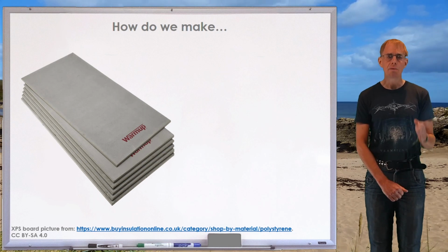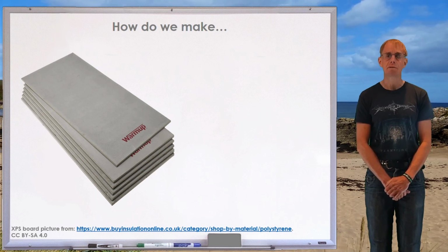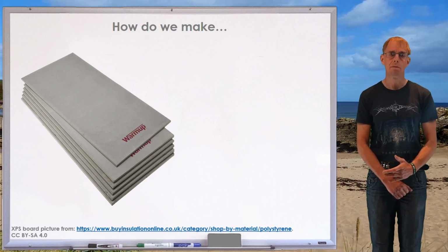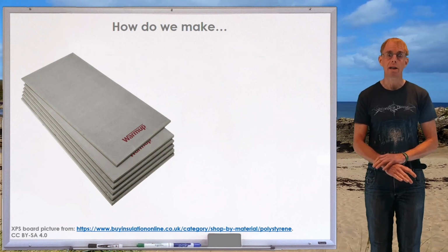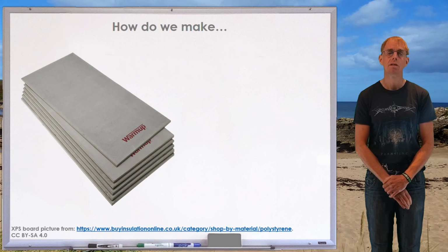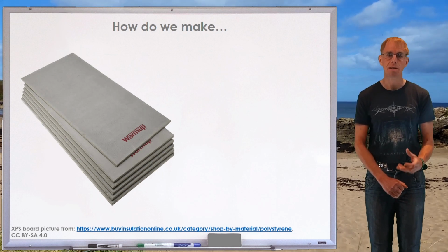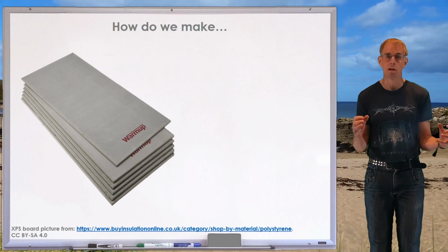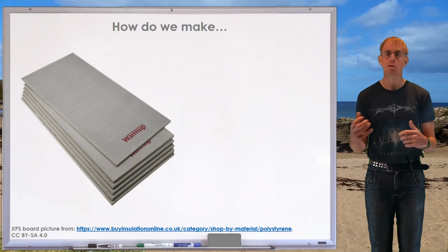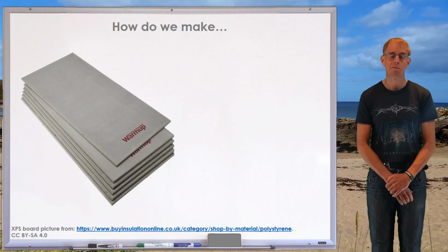And so, if we were to zoom in onto one of these board-based products, what you'd see is effectively a foam structure. And by a foam, I mean that you've got a matrix of a material, usually a polymeric material, and that matrix is interspersed with gas bubbles. These gas bubbles are either disconnected from each other, which we call a closed cell foam, or connected to each other to form this big tortuous void network, which we call an open cell foam.